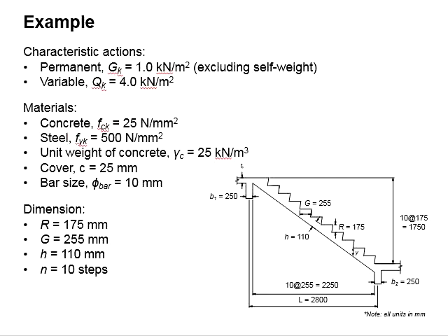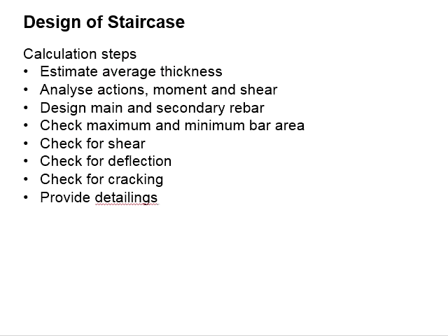You may pause the video for a while to work out the solution. For you to design a staircase, you will need to first analyze the actions, the moment, as well as the shear acting within the staircase. Based on the actions acquired, you are able to determine the moment and the shear within the member, design the main reinforcement bar in accordance with the moment, and then check the shear resistance provided by the staircase.